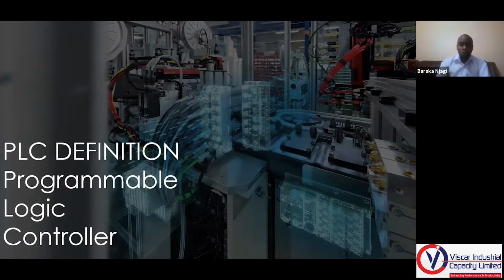So a programmable logic controller is a system or a unit that can manipulate different logics to come up with different solutions, to come up with different outputs. So for example, if I am to run a motor, if I am to run a conveyor, I have my start button and my stop button. If I am to press start, then the PLC should be able to determine that the logic is high. And if the logic is high, then it should actuate the motor that is driving the conveyor. So a programmable logic controller is simply a computer that can exercise and execute logics that have been put in place by a programmer so that it can put out sufficient outputs as required.